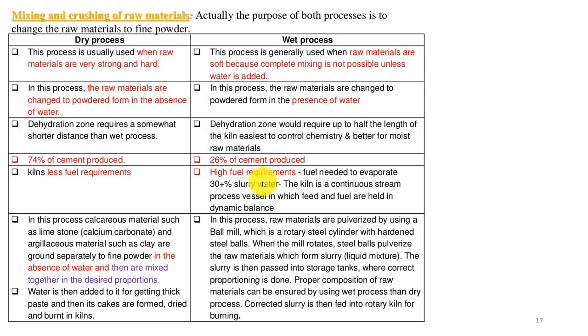In the wet process, you just pulverize your material and then subject it to rotary cylinders. They contain a charge of steel balls in the presence of water. The material is ground into finer particles, after which you evaporate the sludge to have a very fine powder.